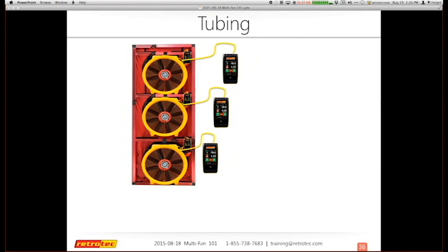And that's why every one of our fans, you'll notice, except the ones we made like 10 years ago, have got 2 Ethernet ports on the fan. One is for signal in, the other is for signal out to daisy chain into the next fan. If you don't happen to have that, you can get what we call a splitter that will take the same signal and send it to as many as 12 or even 24 fans, so that every fan is getting the same instruction, which is go to a percent speed. Back to you. Thank you.